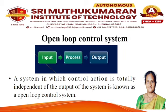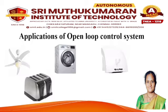Then, open loop control system. It is one in which the control action is independent of the output. That means there is no feedback in the system. For example, ceiling fan, washing machine, electric toaster, hand dryer. In a ceiling fan, the speed of the fan is controlled manually using a regulator. The fan does not check the actual speed, so it is an open loop system.